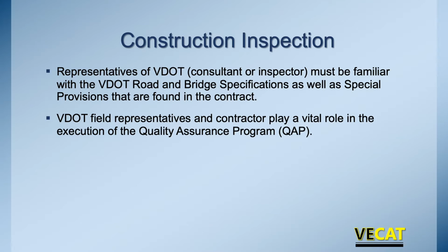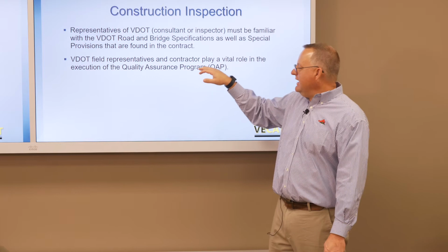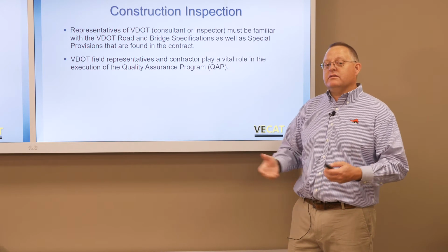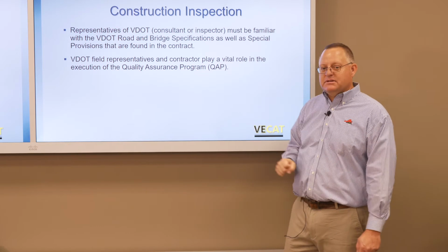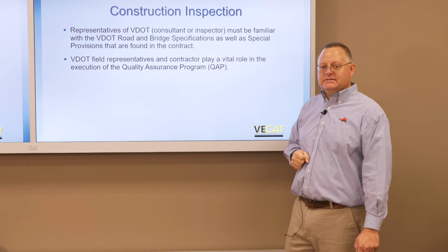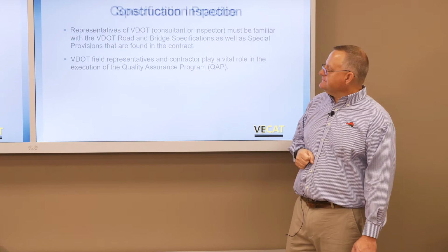You're also making sure that the quality assurance program is being followed. It's a little different with full depth reclamation. This process is still being developed, but you're making sure that the contractor is paid for the work they're supposed to do, as well as that the material is within spec. Out in the field, we're really looking at density, and we'll cover that in a little bit.